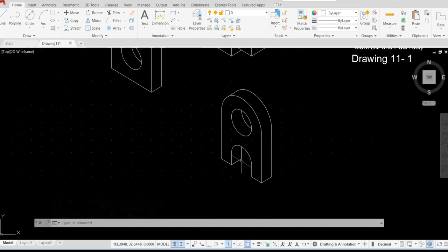I'm gonna do one more, which is the one that has circles on the top. Let me see. So for this one, let's start a line command. So L enter, or just line, pick a point, and here you need to start. We have 4. So 1, 2, 3, and this is 4.